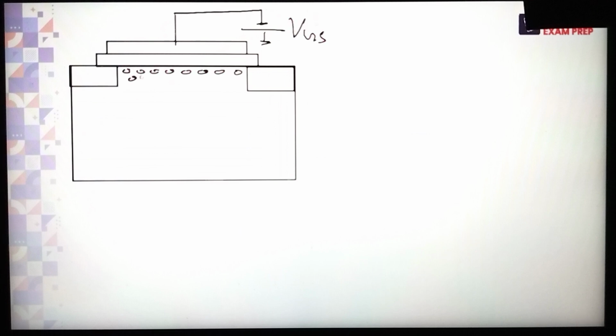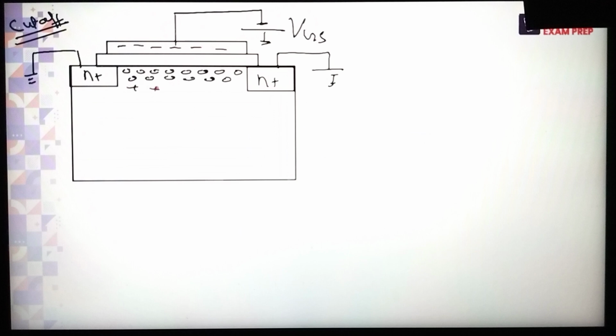When we give a small signal model, I have already given you the model. What is the model here? CGD, CGS, or between what? Gate and body terminal. We can connect a capacitor between the gate and body terminal, but gate and body terminal we normally use for higher systems. So normally we do not get questions on the gate and body terminal. But we use this model in analog, in high frequency analysis.